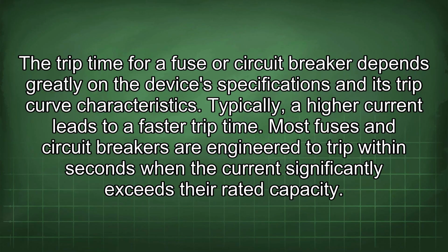The trip time for a fuse or circuit breaker depends greatly on the device's specifications and its trip curve characteristics. Typically, a higher current leads to a faster trip time. Most fuses and circuit breakers are engineered to trip within seconds when the current significantly exceeds their rated capacity.